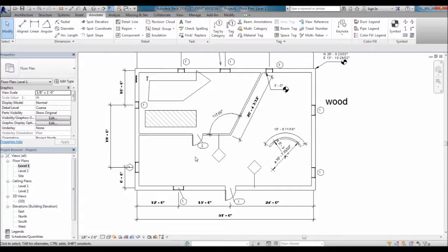So what's important with Revit and with tags is you have to understand how the tag actually works. What the tags are doing is essentially picking whatever object you have, taking a piece of information that's in the properties of this object, and basically just displaying it out here on the tag. So in this case, let's think of this door, door number 1, door number 2. Our door tag here is showing number 1.